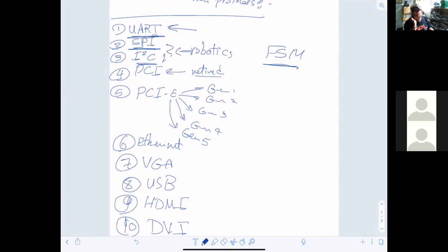I2C, because of the speed of sensors, like, you have a little bit of sensors checking the temperature, then I2C will be used. You have, for instance, pressure sensors, I2C. You have, for instance, radiation sensors, I2C, stuff like that. Because you know what, the physical phenomena this sensor is tracking or observing is really quite slow. So at the end of the day, you have to run at a really low frequency. Okay, then you need to learn how to buffer data, to save data. That's why we're going to learn something called FIFO.